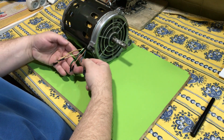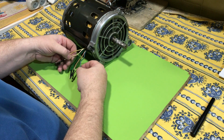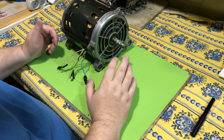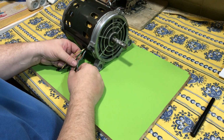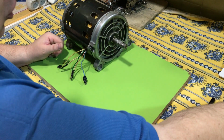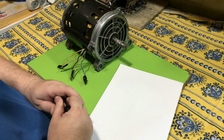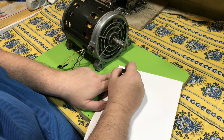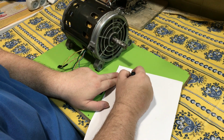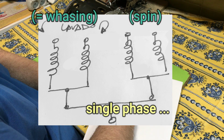In this case, this is a 5 terminal motor. Sometimes there are 6. Having 5 terminals, one can be sure that we are not facing a 3-phase motor. A 3-phase motor normally has 6 terminals for star connection or triangle connection.